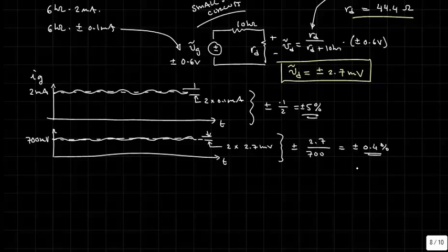Once you have them biased up and you're feeding that resistor diode circuit with a voltage, in this case the 12 volts, if we think of the Thevenin equivalent, say that 12 volts is coming from a battery or some power supply that could vary over some range, you see that the percentage change in the supply voltage or supply current does not translate into an equal percent change in the diode voltage.